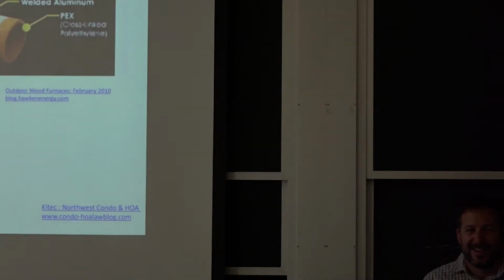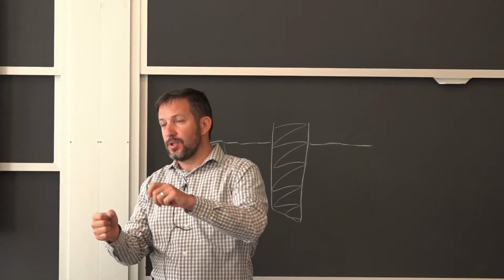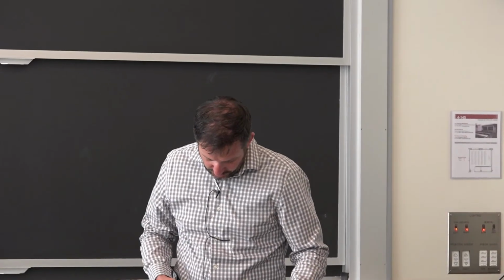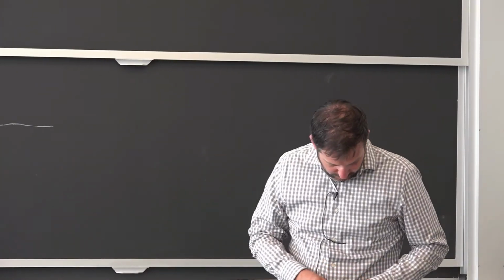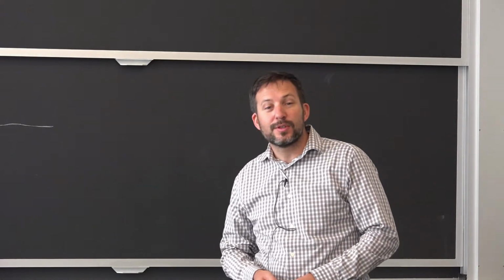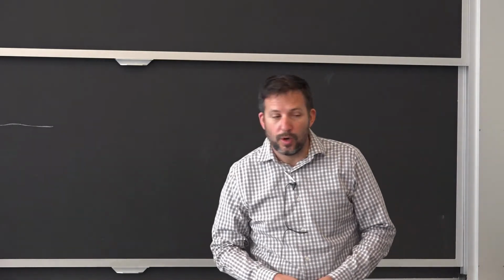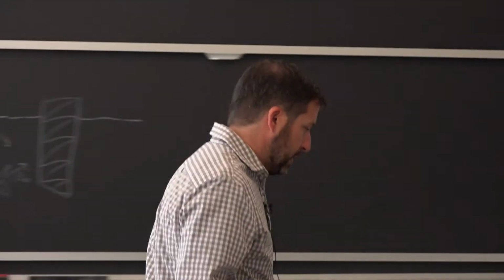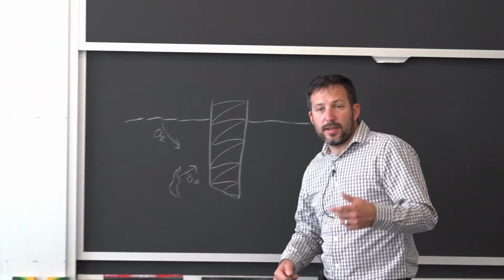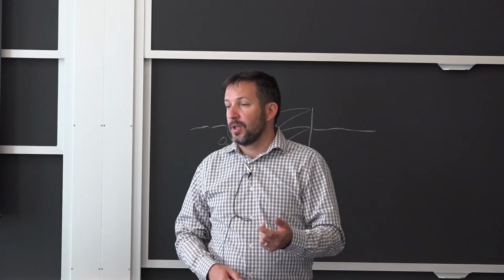Okay, so I mentioned one thing, which is to be able to form it to shape and keep that shape. And the other reason, which perhaps you can now understand better from what we discussed, is that we don't want oxygen to go into the system, because this is a hot water heating system, and it has cast iron or metallic burners where you circulate the water, boilers, and if there is any constant supply of oxygen, that piece of steel used at very high temperature is going to corrode.